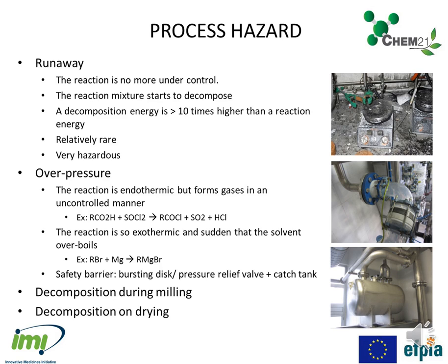As a chemist, the first process hazard you have in mind is the runaway, when the reaction is no more under control and the mixture starts to decompose. The decomposition energy is circa 10 times higher than the reaction itself. It is relatively rare but quite dangerous.